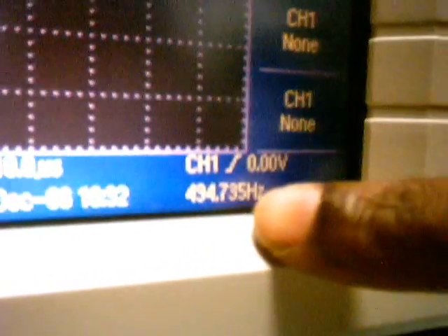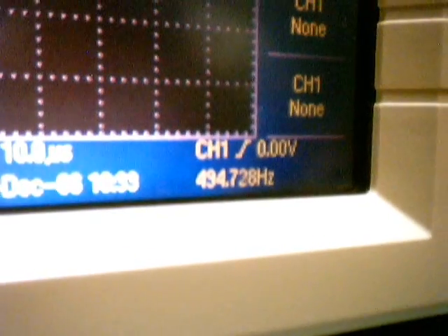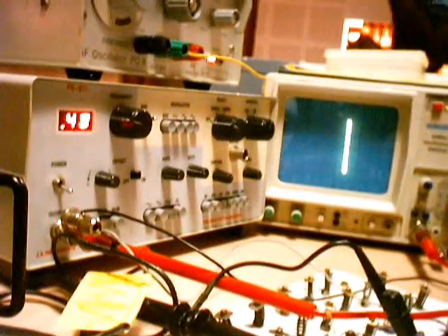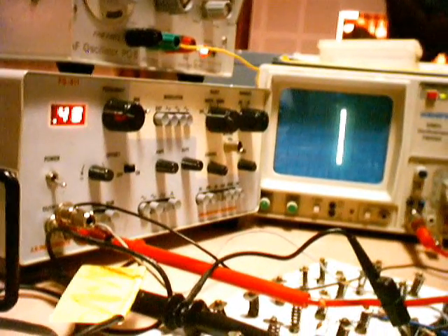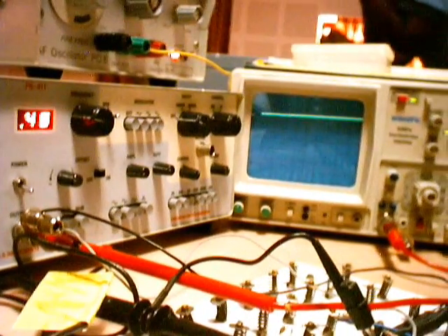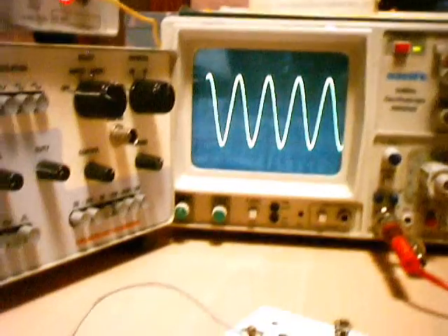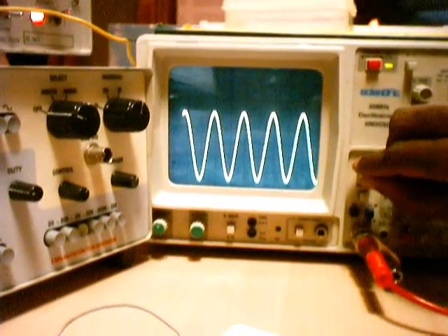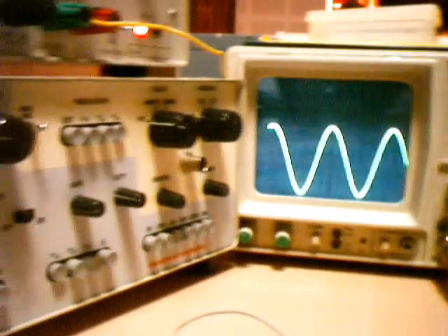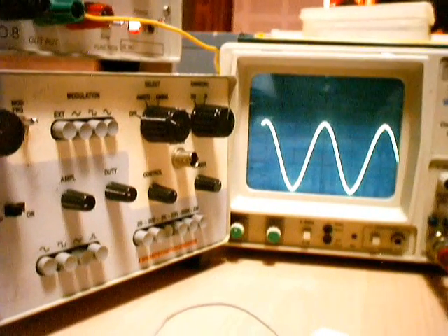That we can just do using this. So you can see now the frequency from the DSO is 494 hertz, which is close to the required frequency. Now we need to find the output voltage to find the roll off. So let us just find the output voltages. Before we measure the output, we should ensure that the input voltage is constant at 5 volt, which is there here. Let us also measure the output.